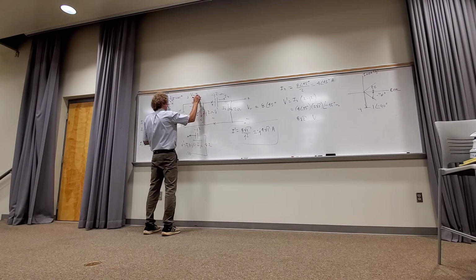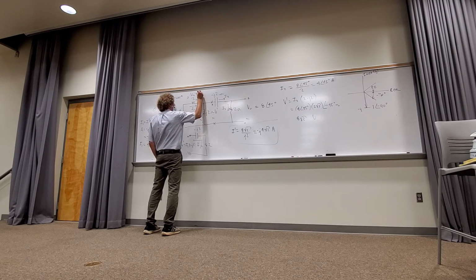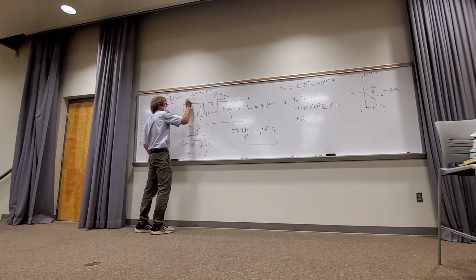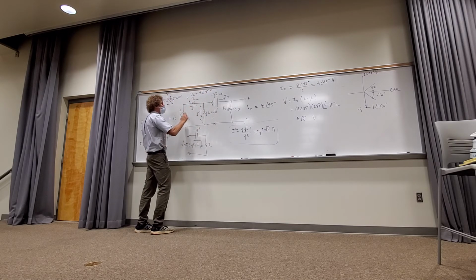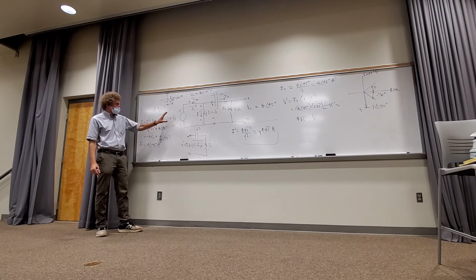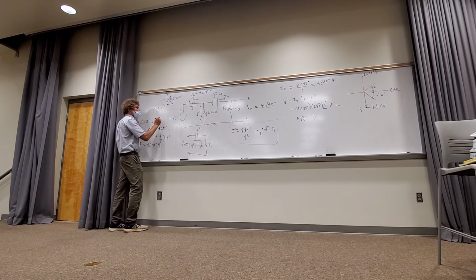Or this voltage V2 here, since this is 2 ohms, would just be 4 at an angle of minus 45 times 2, or it would be 8 at an angle of minus 45 degrees volts, right? That would be from here to here. Correct, class? All right, now, wouldn't VS right here be equal to that voltage, plus V prime? Y'all follow me?